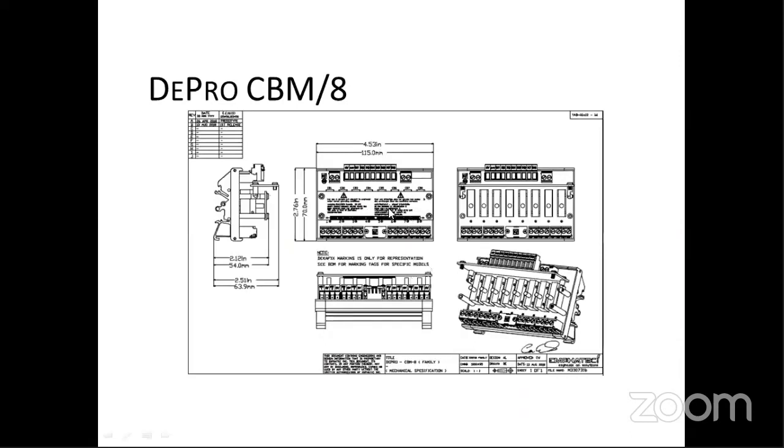This just shows that to access the breakers, to reset them, there's a hinge cover here on the front, and you pop that, you loosen 2 screws, open the cover, and you can reset your breaker, put the cover down, tighten the screws again. The whole cover and screws thing is because the CSA UL requirements want to slow you down so you can't just reset the breaker without checking to make sure the area is safe and there's no explosive gas. So there's warnings on the front. Then you loosen the screws, open it up, reset your breaker when you know it's safe, and close it up again.